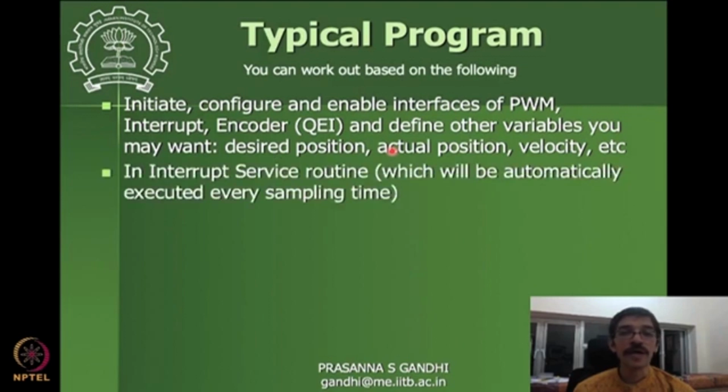Then in the interrupt service routine, this is very important, we'll need to do these three operations that I was talking about. You need to make sure that no initiation or configuration functionalities from TIVA come into this interrupt service routine. Configuration or enabling of interfaces should not come in the interrupt service routine. It should just be, for example from the QEI interface, reading the value of the encoder or reading the speed of the encoder, whatever function is there, because that is a thing that will be continuously changing.